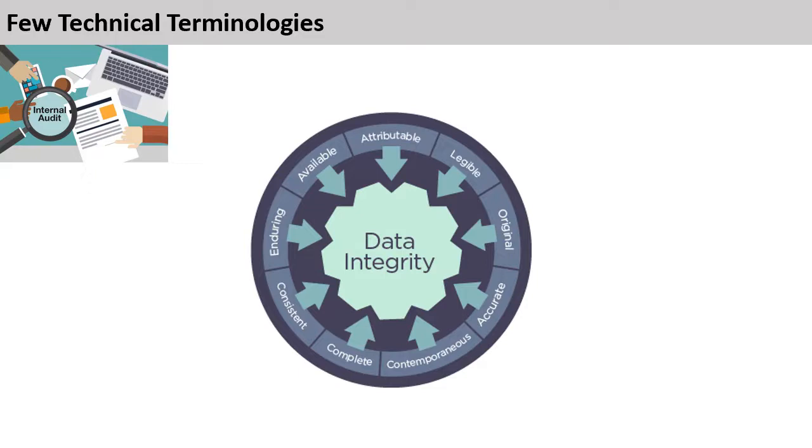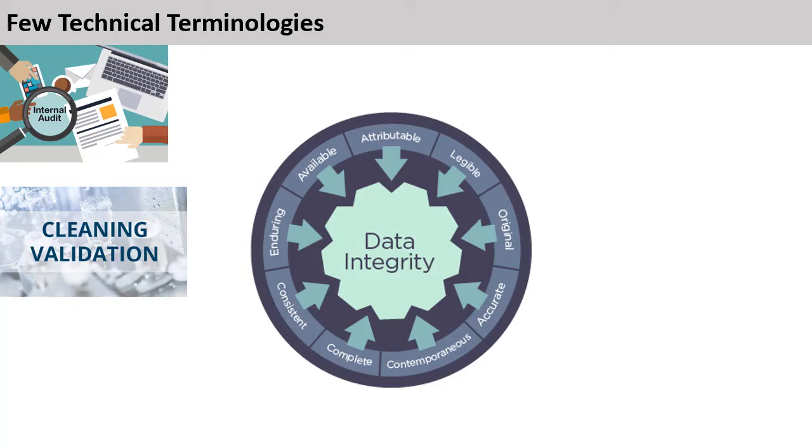Cleaning validation. It is the documented evidence which assures that the cleaning procedure is effective to clean the surface consistently to remove the residue of the product, microbial contamination, and detergent to acceptance level. It is essential to ensure that product is free from any cross-contamination.